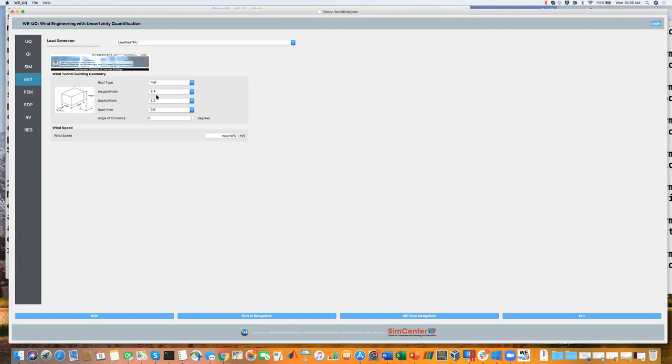That is a limitation of when we use the TPU database: the building might not fit exactly with your building dimensions. And then for my wind speed, I'm going to create a random variable again. I'm going to call it min wind speed. So instead of the gust wind speed that was in the stochastic event, TPU takes a mean wind speed at the 10-meter height.